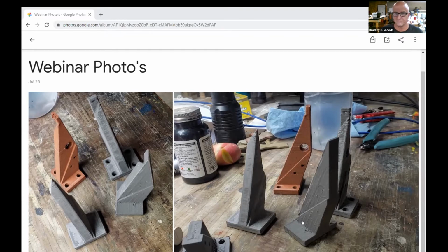But ultimately, this would just be designed differently. Rather than having the big blocky chunks that are mostly there because of the way they used to be manufactured, which was on a milling machine or a cast, it would be better to remove as much of the material as possible and just minimize the amount of material used in the part.